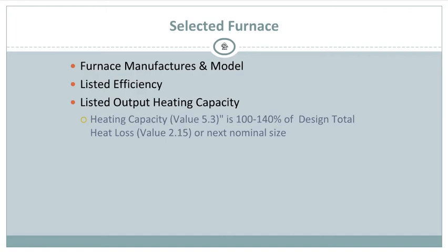They burn the gas a lot higher, and they produce a lot of condensation, so you're going to have a drip pan at the bottom to catch all this condensation. Either you need to have a drip pan, or you're going to have a line that goes directly into a drain system, so that condensation from that heating equipment can drain and isn't causing any damage sitting there, because it's going to be water sitting somewhere if you don't deal with it directly.